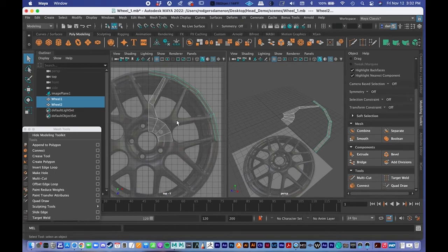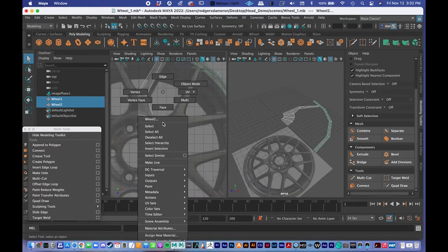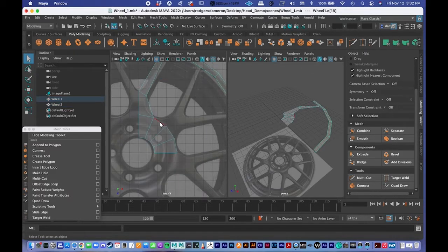And so now I'm going to do this spoke right here. Similar process is I'm going to select these two edges. Notice that this isn't along an axis that mirrors, so I probably won't need to worry about that world local thing when I extrude, most likely.